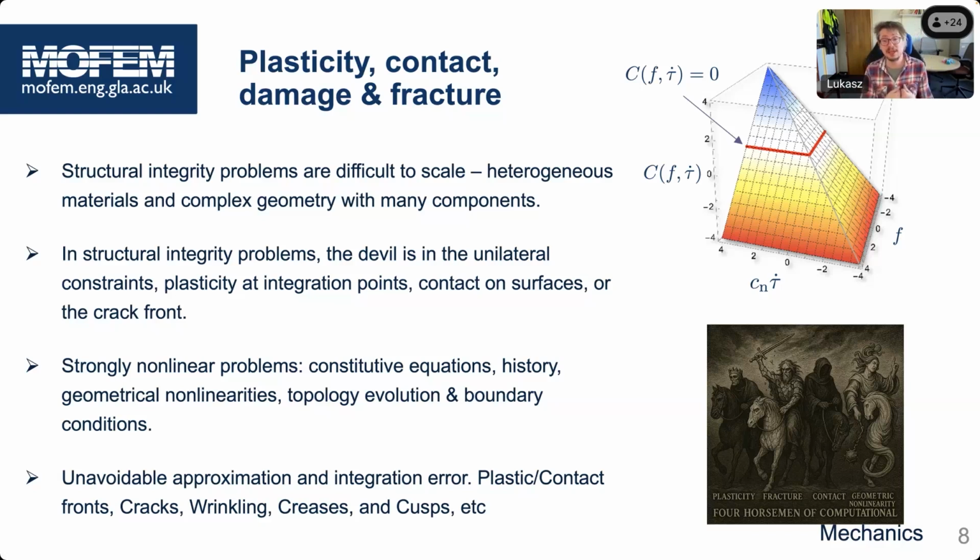In each of those cases, you need lower approximation orders. You will use the higher approximation orders to have a certain structure of the matrix, the size of the blocks, in order to solve the problems faster. But at the end, you need the lower approximation orders because of those problems with plasticity and geometrical nonlinearities, which generate the instabilities.